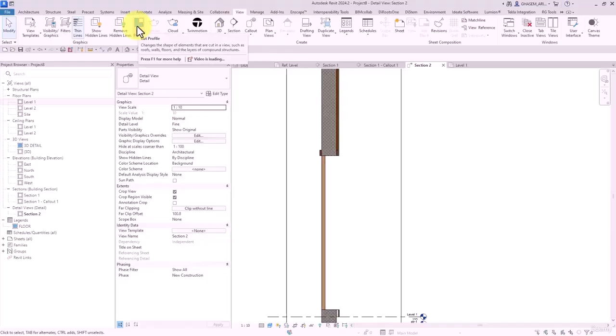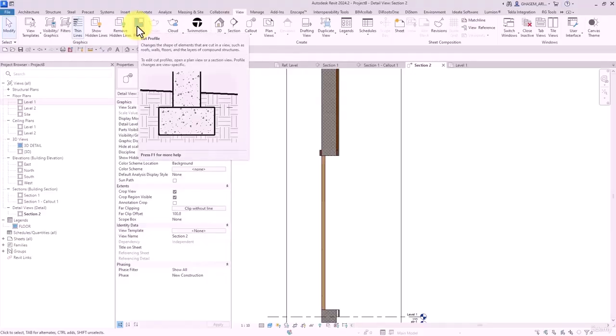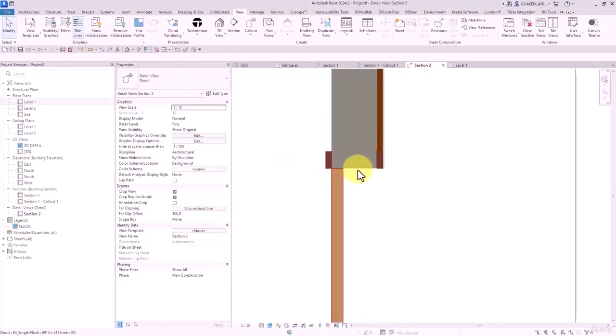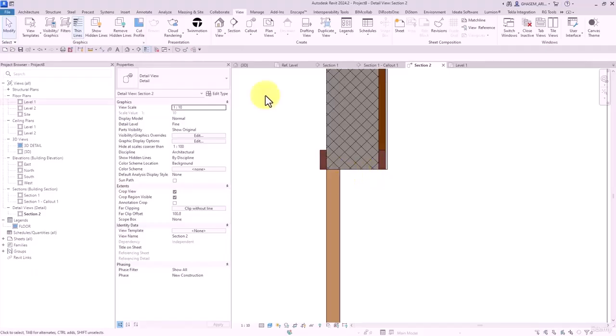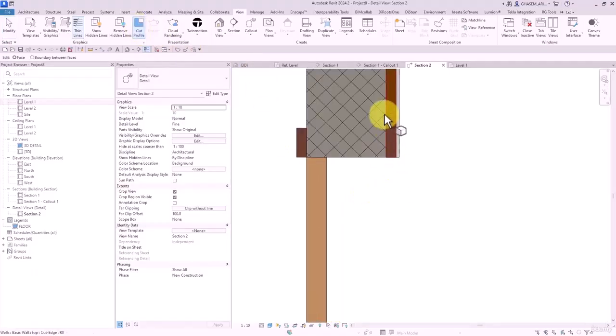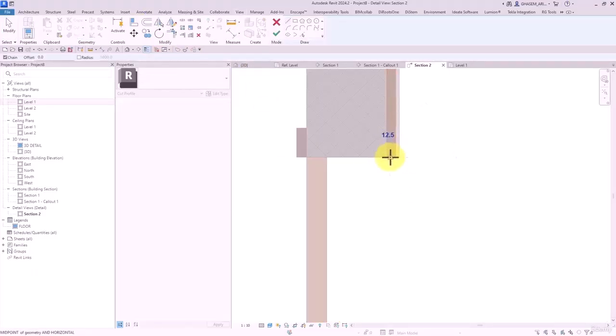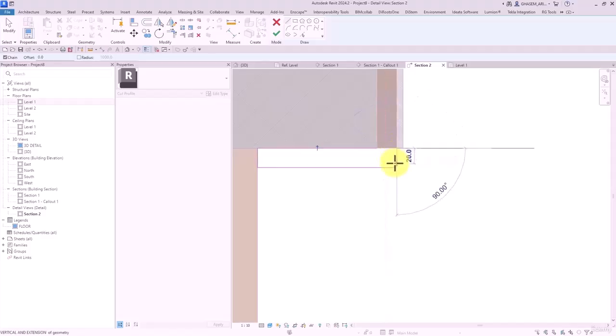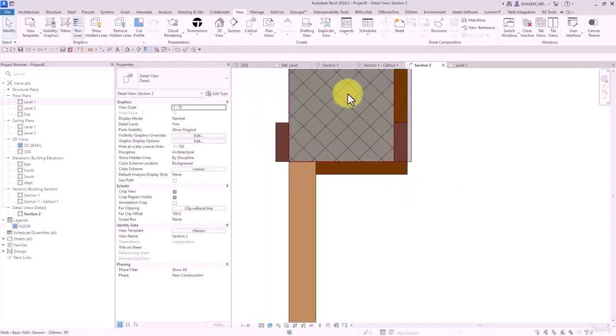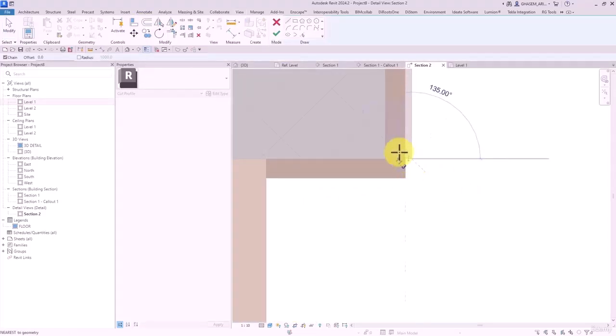Here we can have an interesting technique. We can use cut profile in view. It's just for having more detail. I mean presenting more details. I want to bend this finishing layer and connect it to this here. I select and click on this. Thickness 25, so till here, 25 downward, again here, and like this. This arrow should be to the inside. It should always be like this.